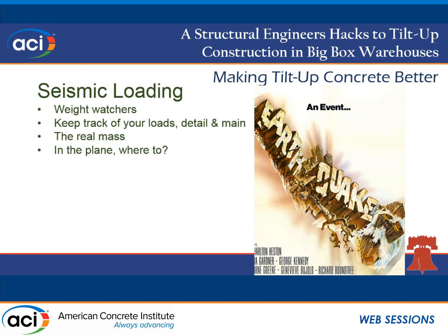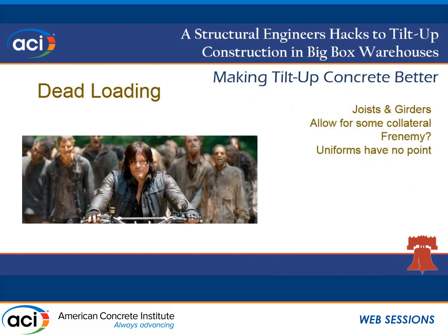Probably the most cost-effective way of dealing with it is stitching panels together. So you got 2 or 3 panels, so you got 90 feet of shear wall acting uniformly to overturn, versus trying to anchor each individual panel for the 15 or 20 kips, and then trying to figure out at the foundation, well, if I've got 20 kips up and I got 20 kips down, how the heck do I design that grade beam for, and how do I get that force across the joint? So most engineers, they try to stitch panels together, but be warned, those stitching connections can crack, they can interfere with your vertical reinforcement. There's a lot of nuance and fun that gets involved with that.